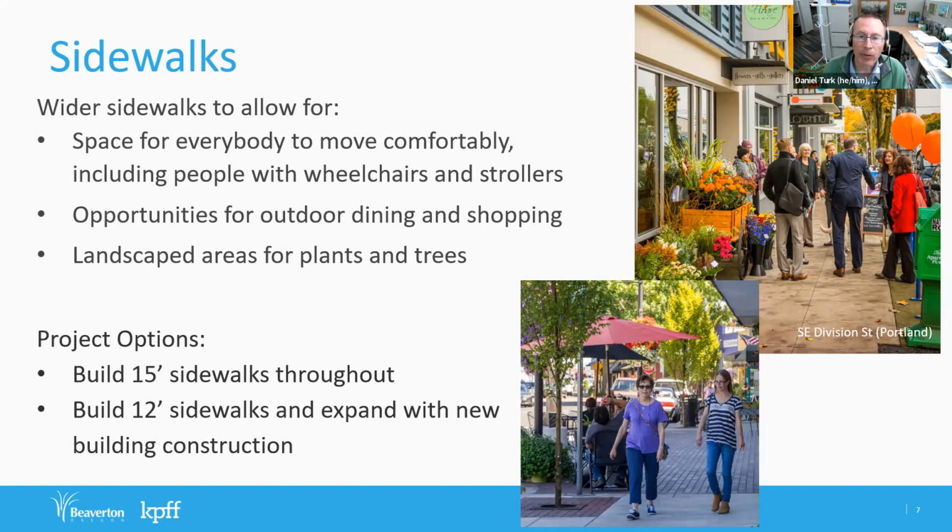The city could build 15-foot sidewalks throughout the project, but another option is to build a narrower street with only 12-foot sidewalks and then require new building construction to expand the sidewalk to 15 feet. Now, 12-foot sidewalks would accommodate all the uses that I mentioned, but the 15-foot sidewalks would provide more room for people to walk and gather and more space for storefront activity to liven the street.